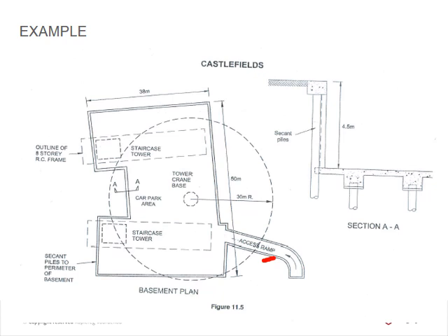Then you've got a second section, your resources: your supervision, your labor, your plant. You list all those items that you need to sequence here, and then they combine their health and safety within this method statement. So you can see significant hazards, and then you've got control measures. So there's their health and safety section incorporated, and then they've got their PPE there at the bottom.